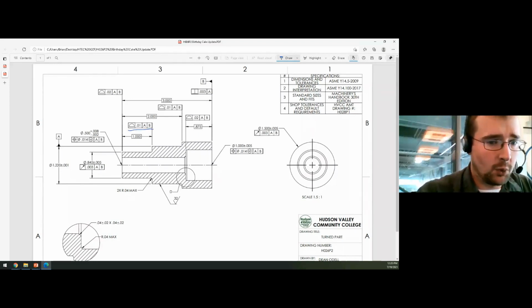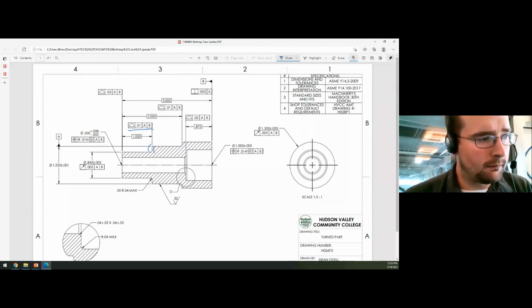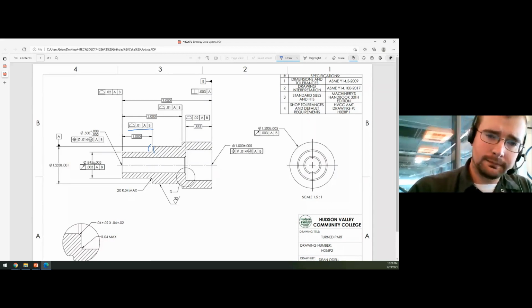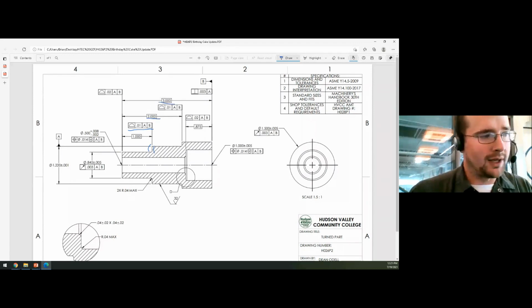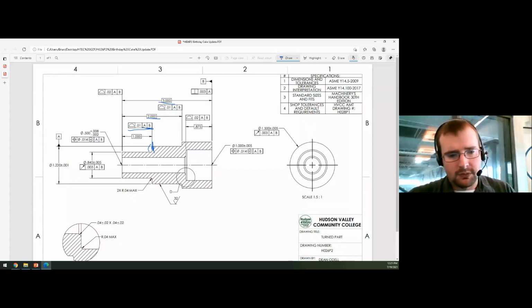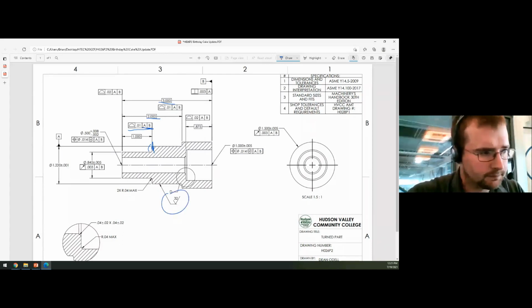Simple depths and what that means and the tolerance zone to what, and also notice one thing that Mr. Odell is very big on is that he changes where the basic dimensions come from and how that changes where the surface needs to be inspected to based on the datum reference frame, or based on the feature control frame, sorry. All right. So these are some things, surface finishes we get into.